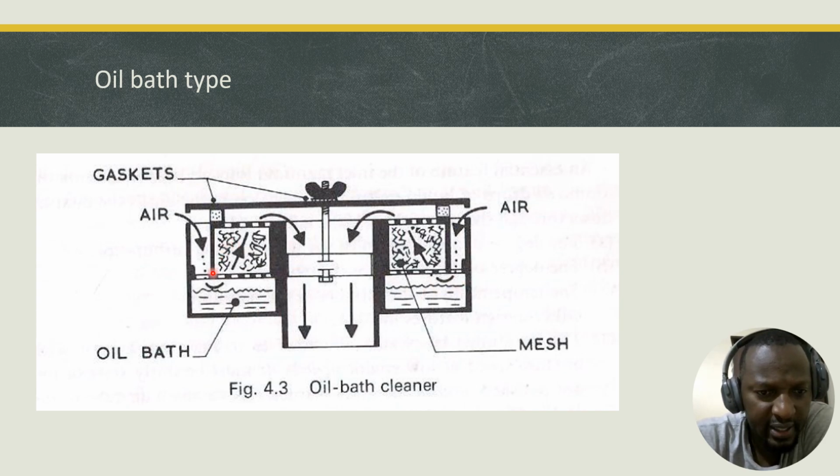Above the container is a sieve that has several slots that allow air to pass, and on top of it is a wire gauze, similar to a rough, coarse steel wire, that surrounds the air cleaner. So this air cleaner is cylindrical, and in the middle is the main air tube. So air comes in as the pistons are moving up and down.